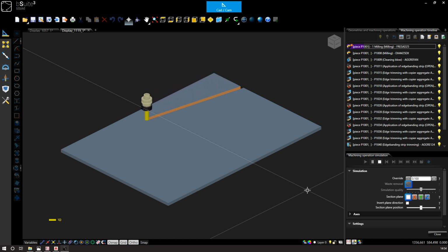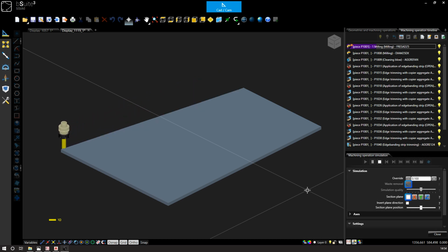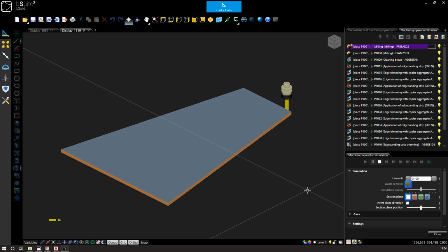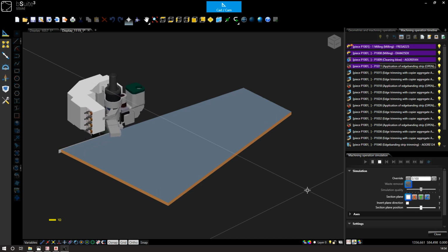Because imos is using a condition-based logic, we can apply filters to parts and certain machinings so that they will always be applied dependent upon the type of machining required. This means that the correct tooling, lead in, lead out, speeding, diameter, and feed rate can all be passed directly to the program from imos, with little application being needed within B Suite.